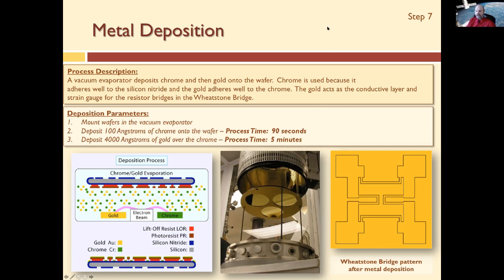And there you see your wheatstone bridge that's basically photoresist that's been coated with gold and openings that have been coated with gold. So these openings here, okay, have gold stuck to the silicon nitride. This gold here is stuck to the photoresist. Okay? The reason you see these black lines is the light doesn't reflect from vertical structures back into the microscope. So it's a well-defined edge, right?